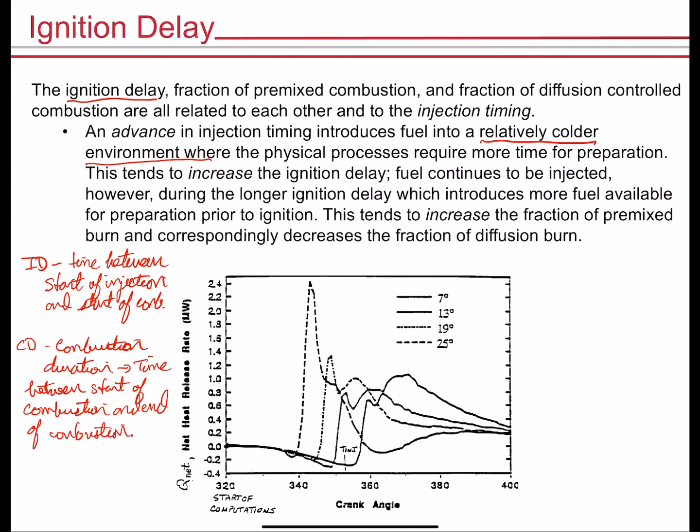You know physically, based on your own experiences, that if you heat something up, it's going to be a lot easier to atomize it and vaporize it. So if you cool it down, it's going to be harder. It's going to take more time to do those processes. So when you introduce a fuel into a colder environment, you increase the amount of time that it takes to physically prepare the mixture for burning, and that will increase your ignition delay.